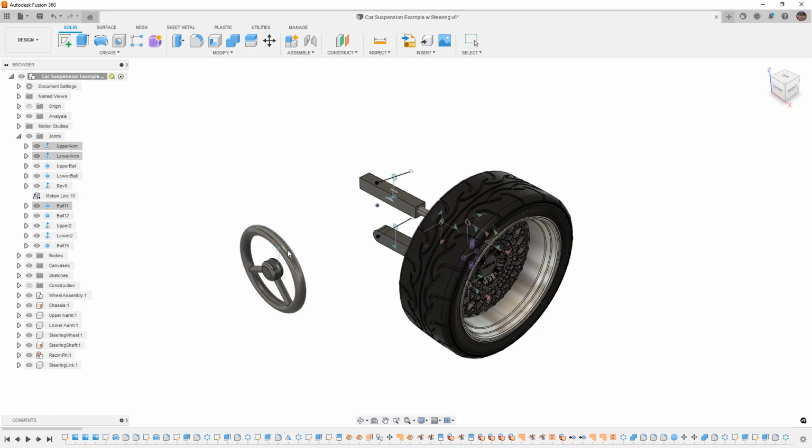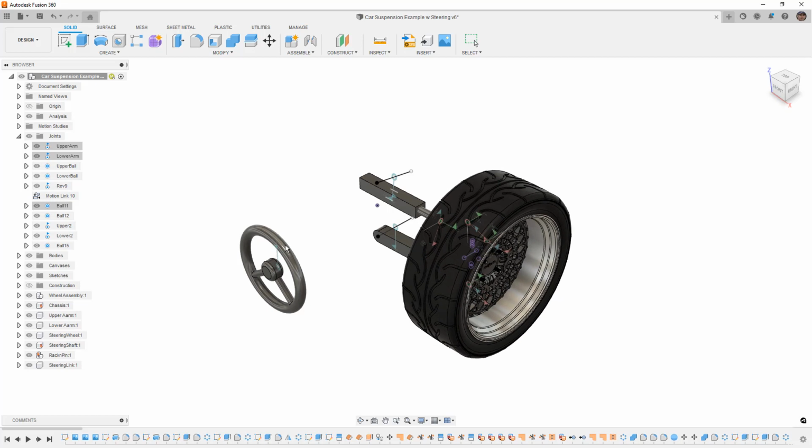We don't want the steering wheel to turn because when we're talking about bump steer, typically we're talking about what happens as the suspension travels, but the steering wheel doesn't turn. Now, there are, of course, nuances to this if you're talking about going straight or if you're talking about turning. It's a complicated process because when you turn to the left versus turn to the right, the tires are going to turn more or less based on suspension geometry. We're not going to get down into that level. We're going to talk about some of the basics looking at just bump steer in this example.